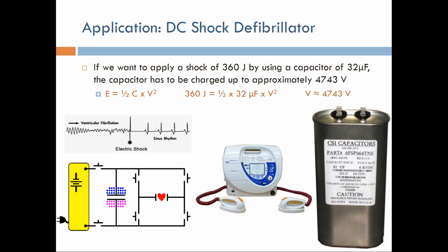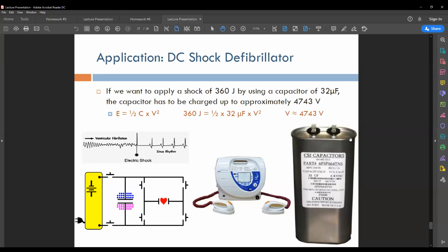Each capacitor, you have to make sure that it's discharged before you try to work with it or touch its terminals, okay? Okay, so do you have any questions?